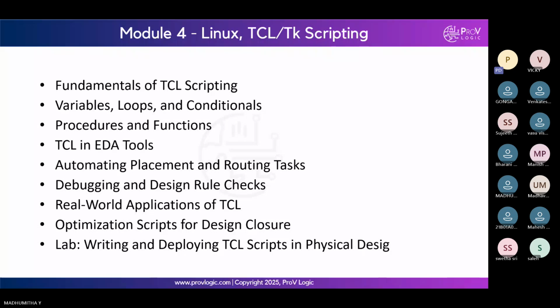So the present data will be missed out. That is why we use the same edge check for hold check. To check the data present in the flip flop, we do same edge hold check.